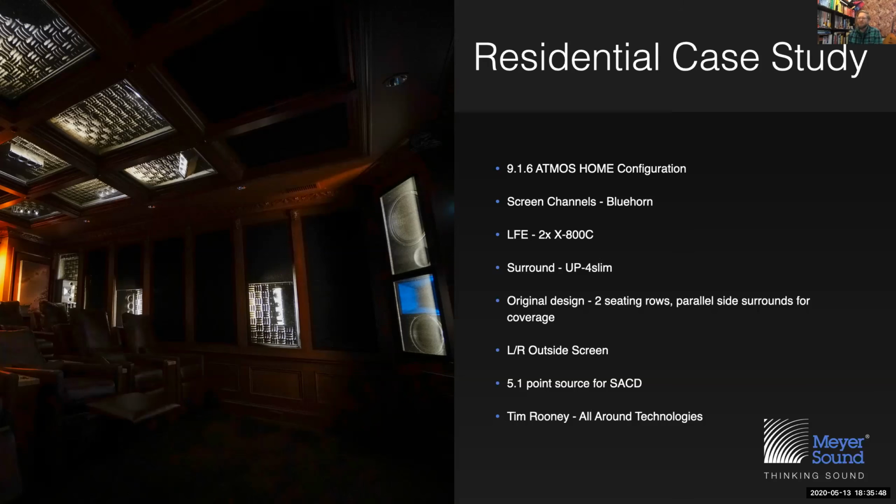It just made me happy that they got what they wanted. And the same location worked for that point source side rear surround, that HMS5. You can see it's mounted sideways. That's one thing I hadn't made a slide on, but just to mention it, the HMS series has a built-in 15-degree down tilt. So when they mounted that sideways, that 15 degrees aimed that speaker into the room towards the primary listening position. From this photo, we're looking right down the barrel of the horn. So they got it to where it needed to be.